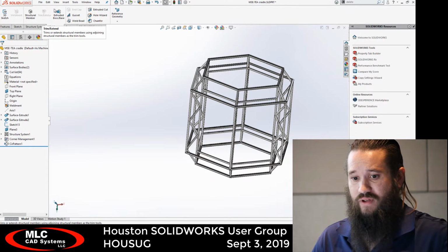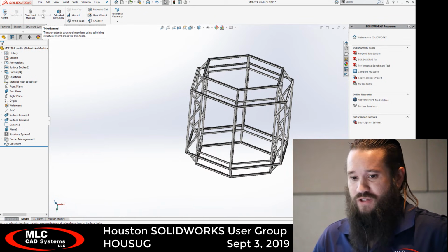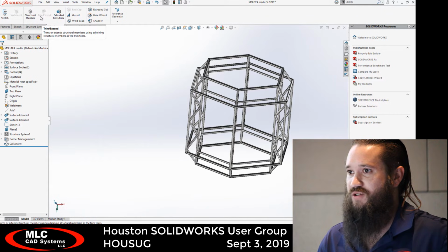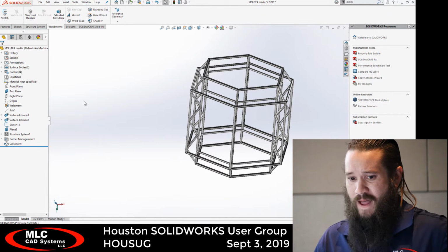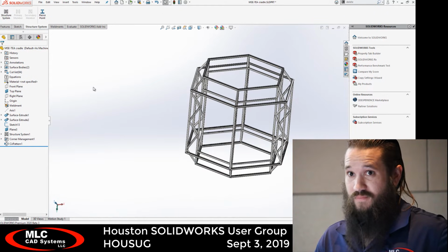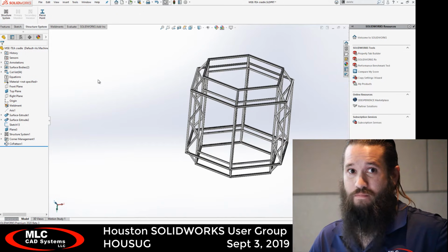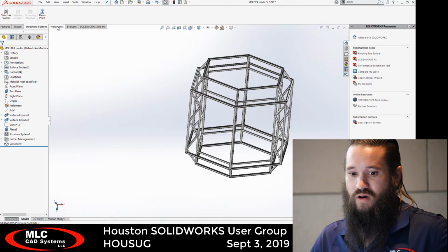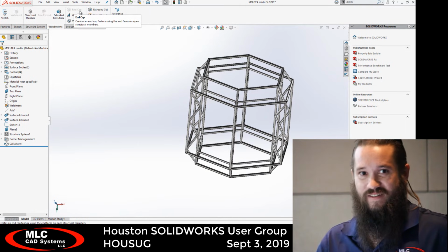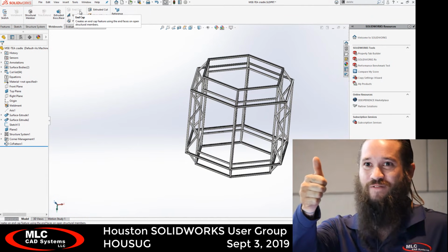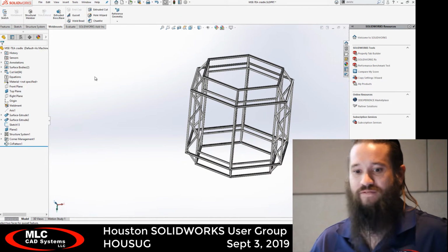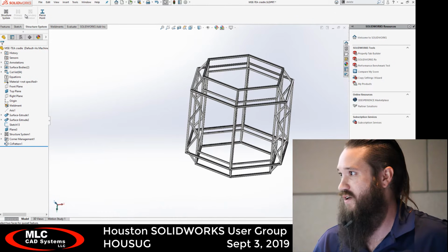I use end cap and the trim extend quite a bit. So I was kind of confused when I first came into structure systems, wondering how I'm going to do all that extra stuff, right? You'll notice that structure systems does not have any of that. So that's the first big difference. So can we use end caps on structural members? You would think it's the same profile, but you can't. You can't use the trim and extend. You have to only use the tools available here.